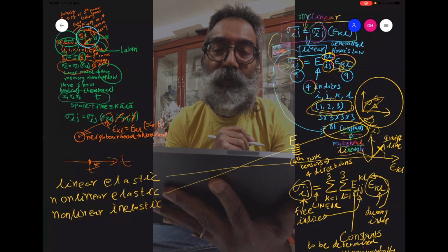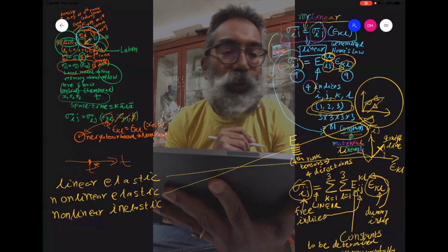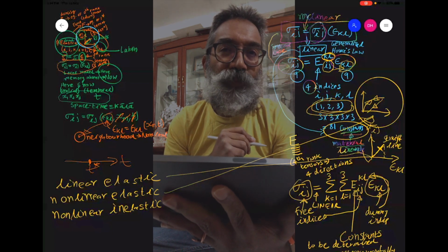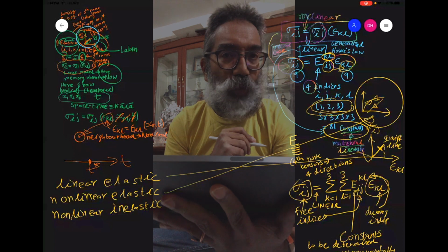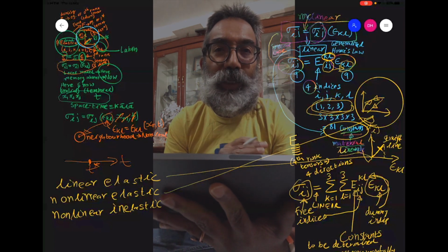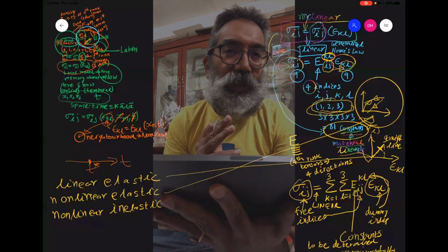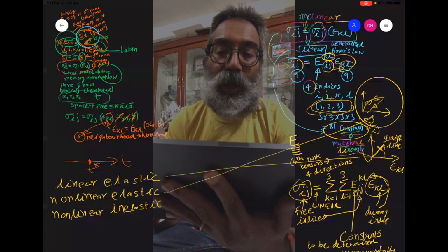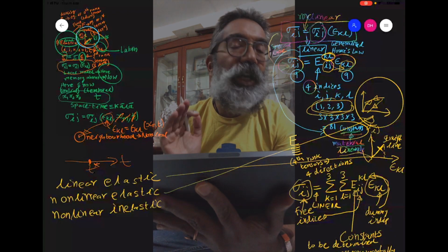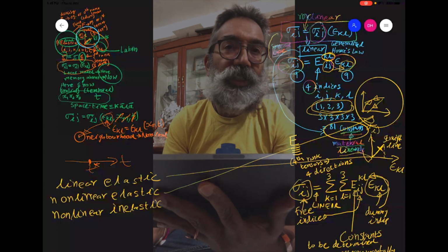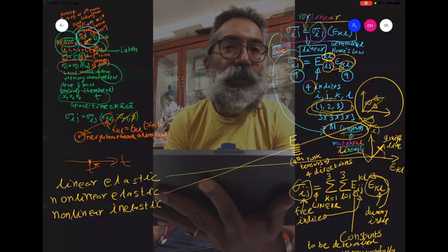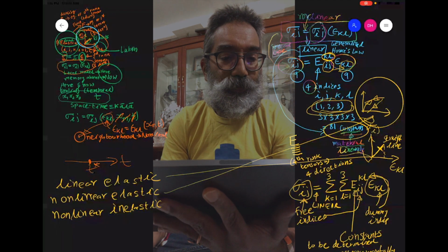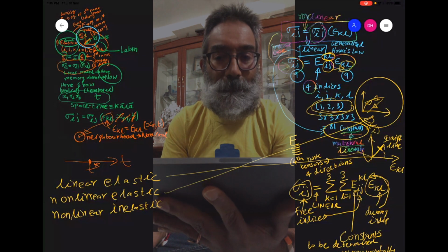Okay, so this is the generic level at which we are. We will include certain aspects from the speciality of the material in terms of its geometry and the planes of symmetry involved to reduce this further. But at this stage, where we are only saying that it's elastic, non-local, no memory, material linearity, you can have in general all these 81 constants being non-zero. So every stress component depends on every other strain component apart from its own kind. Okay, sir. Yeah. Anybody else?